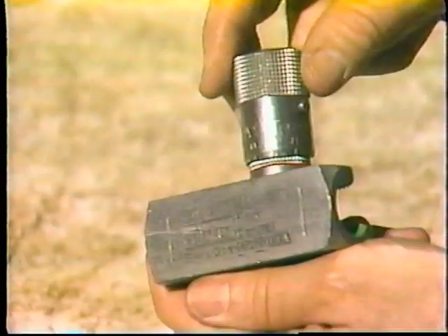Remember the regulator we talked about earlier? Its job was to portion out to a certain leg in the circuit just the pressure required to equal the load resistance plus a little more. This additional pressure is used to develop airflow. Even so, pressure regulators are not used to vary actuator speed.